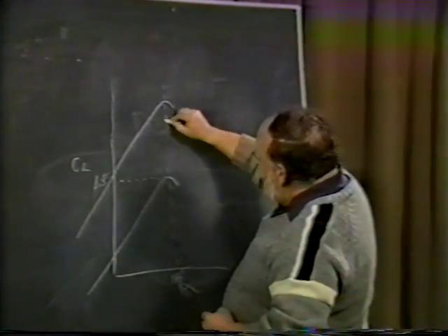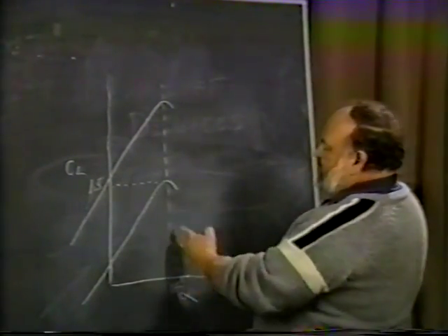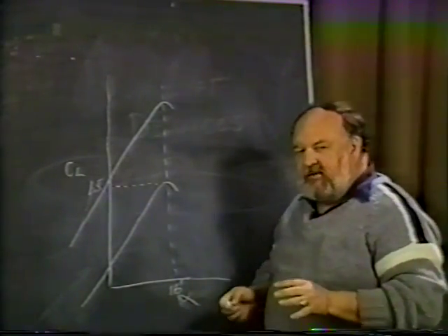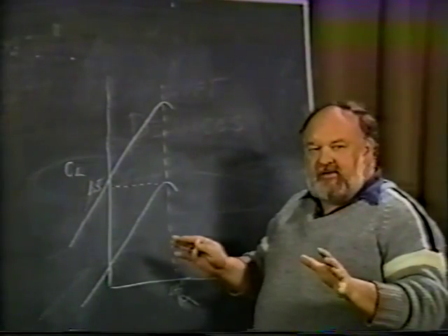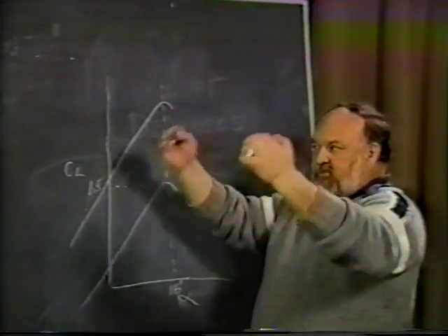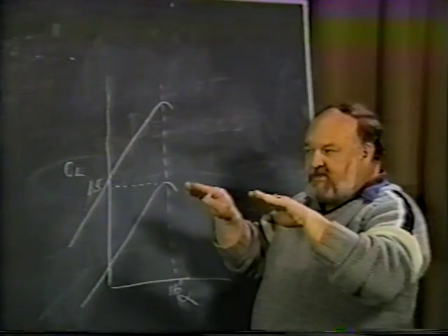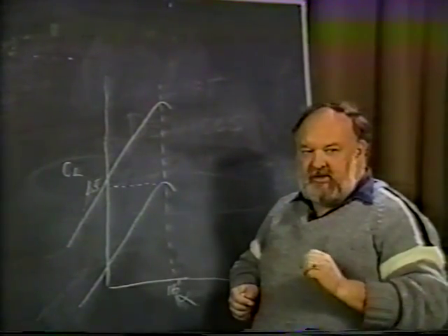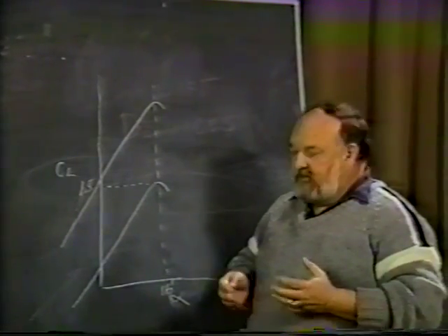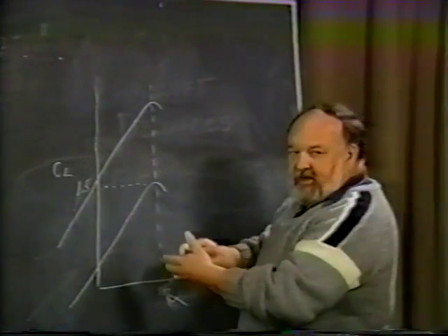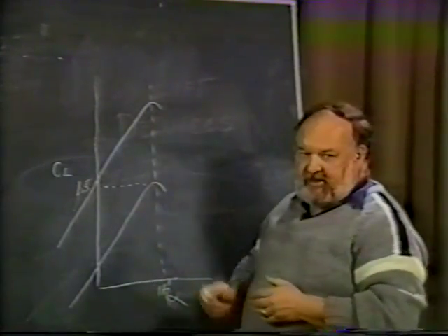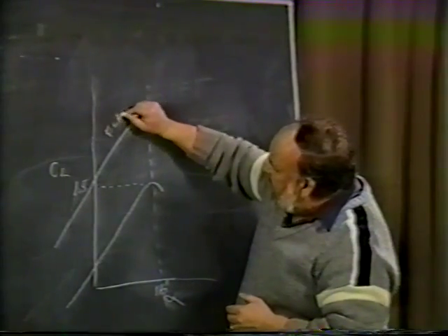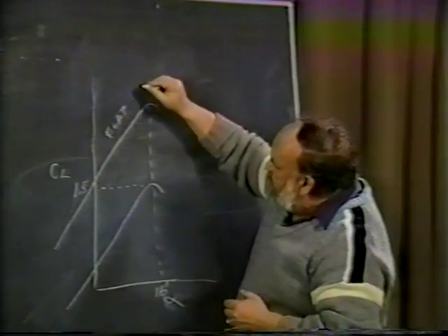But in most cases, the angle of attack that the wing will stall at will be pretty much the same. And this is somewhat understood in the fact that here you are with the trailing edge of the wing, you put these devices to induce more air to come over it, but the wing itself can only go to so much of an angle before the flow over the leading edge causes separation. So the flaps produce a lot more camber, a lot more lift, but not changing the angle of attack itself. So this is because of the flap at the trailing edge,